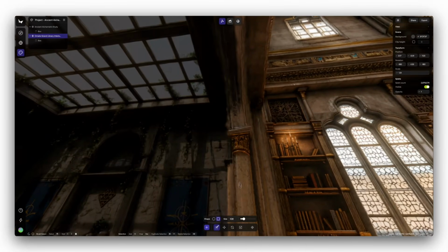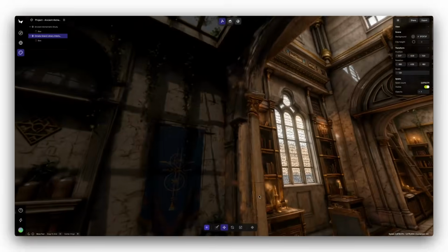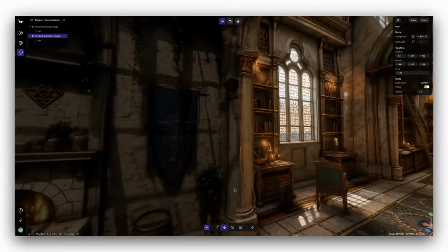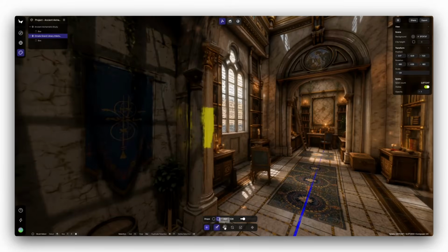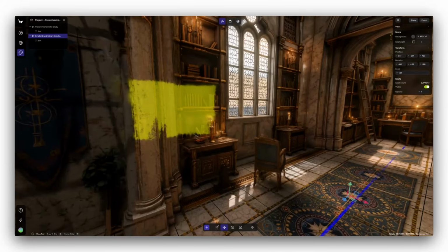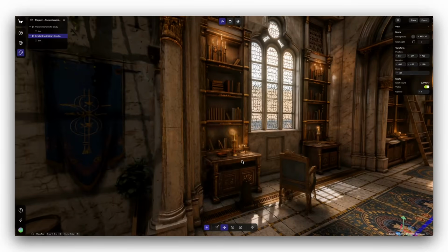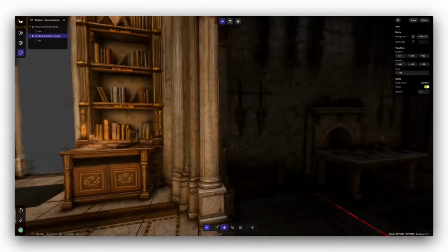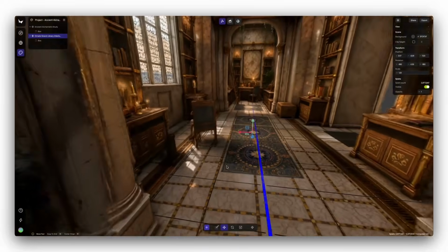One thing to keep in mind when using the brush tool is that it doesn't currently have depth control, so it's helpful to align your camera to only target the splats you want to remove. Anything behind the area you're brushing will also be removed. Also note that once you've made brush edits and leave Studio, any splats you've removed are permanently deleted. For that reason, I recommend using masks whenever possible and reserving the brush tool for smaller cleanup tasks.